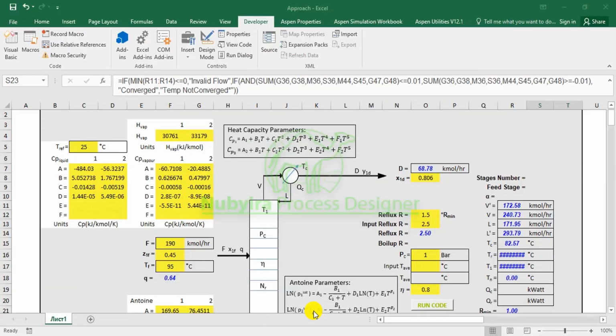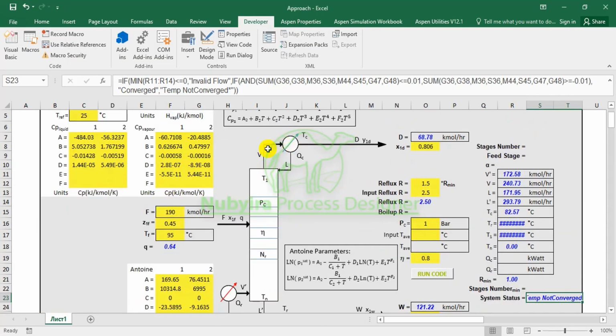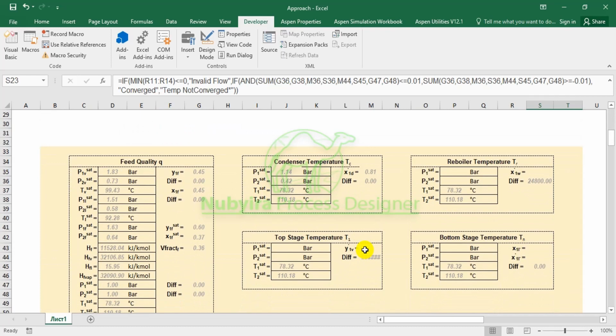We can still use the same mole fraction of the distillate for the vapor that is coming, but it's going to be the dew point temperature of the composition, not the bubble point, because it is vapor phase. That is vapor leaving the stage, the system is at dew point, while the liquid that is leaving is at bubble point. So we are going to do that. I'm going to skip ahead in the video so as not to make it very long.